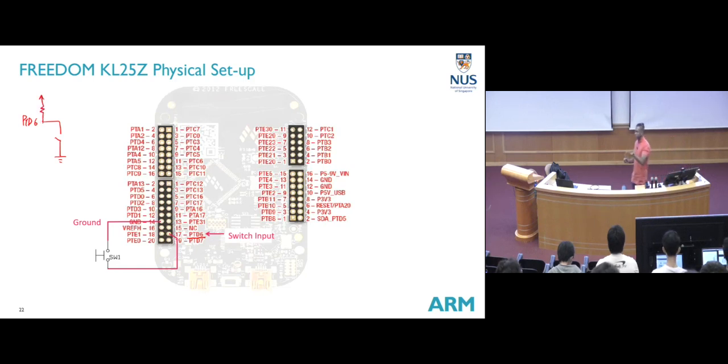This is internal to the controller. I just activate it with the register setting. So there is a pull-up resistor or a pull-down resistor that I can use internally, so I don't need to physically connect it on my board or the circuit. Now, to do the lab for next week: this week's lab is just the GPIO driver, to get familiarized with the board, the RGB LED and so on. For next lab, you need to do this, which means you need to solder the header pins.